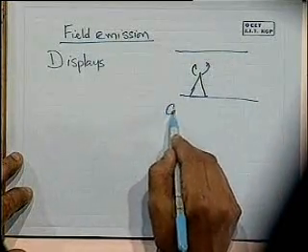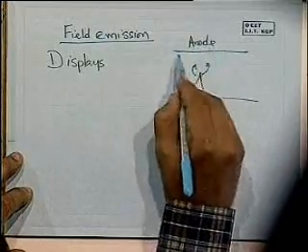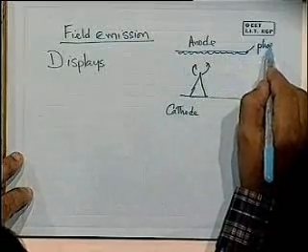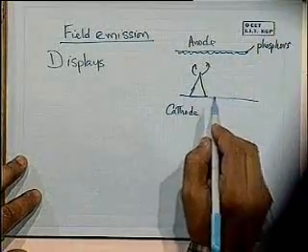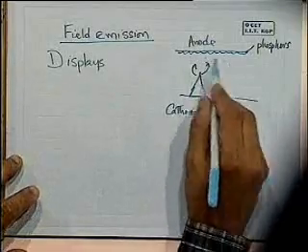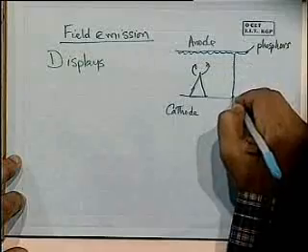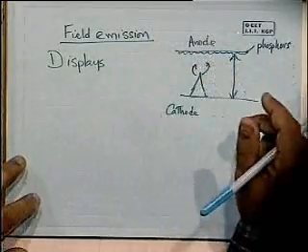So we'll have the cathode here and an anode layer where there is some kind of phosphors that are coated. And when we apply the voltage, remember it's field emission, so very high voltage, and the gap between these can be kept very small so that the field is appropriately very high.